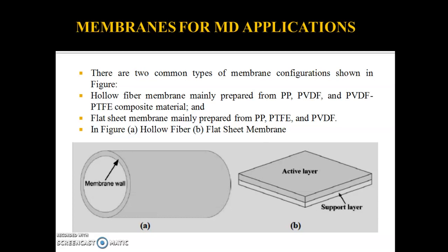If we consider the spiral wound membrane, in this the flat sheet membrane and spacers are enveloped and rolled around the perforated central collection tube. As you know the structure of the spiral wound membrane, the feed moves across the membrane surface in an axial direction, while the permeate flows radially to the center and exits through the collection tube. The spiral membrane has good packing density, average tendency to fouling, and acceptable energy consumption. That is the criteria for the membrane selection, right?